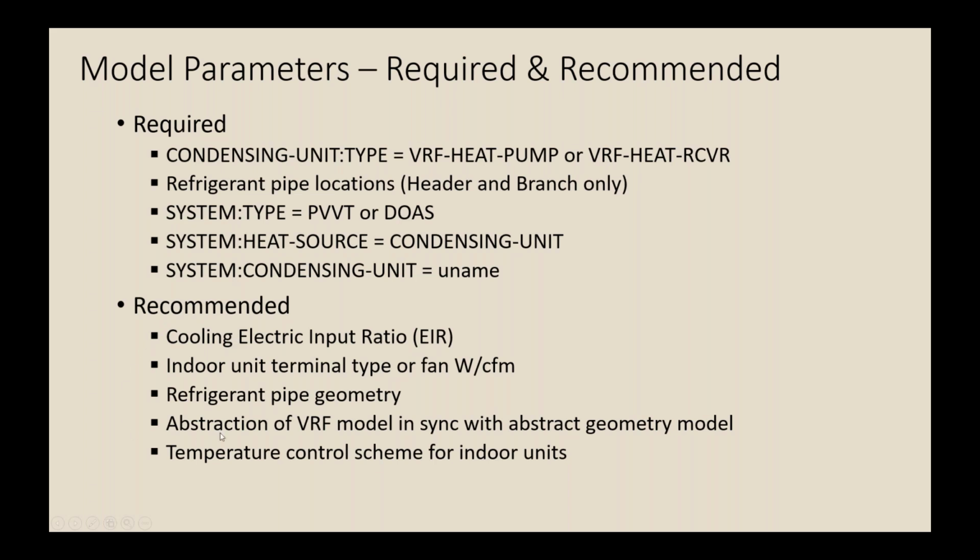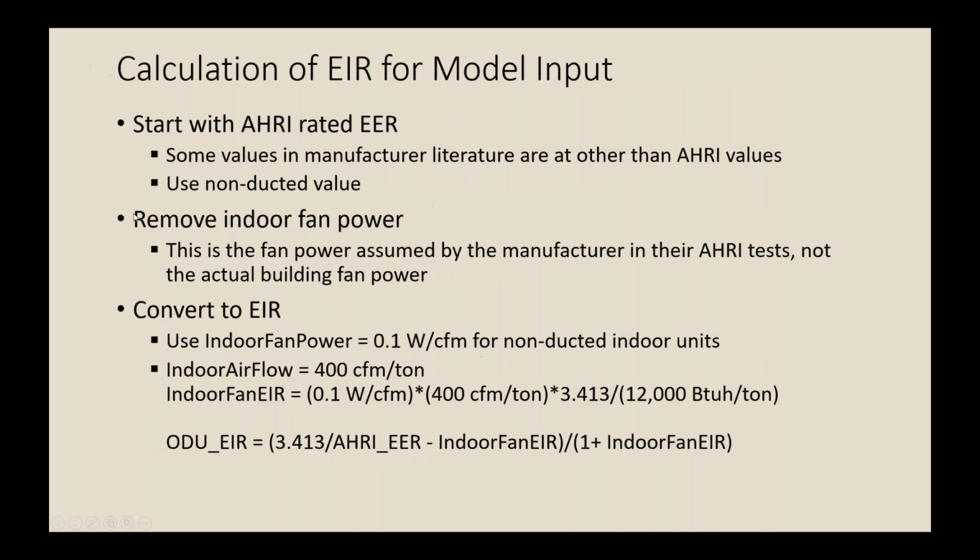Okay, so then there are these additional recommended entries into the program, and I'm going to talk about these in the next few slides, so I won't read through each one. The first is calculation of the electric input ratio for model input. There are a few things you have to be aware of and careful about as you collect data from manufacturers' literature. First, you want to locate AHRI-rated values of EER in the literature.